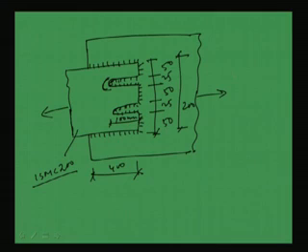So, these will be the details of the slot weld, how we have designed. To find the maximum load carrying capacity which can be carried by the plate, meaning this ISMC section, as well as by the welding joint, to withstand those loads we have to design the welding joint in this way with the use of slot weld.